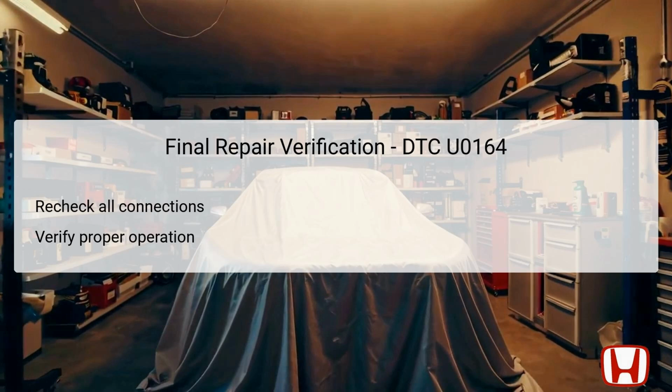It is also advisable to test the climate control unit's functionality thoroughly after repairs have been executed. This includes checking all features of the HVAC system, such as heating and cooling outputs, fan speeds, and any other relevant manual controls to confirm they are functioning properly. If all features operate correctly without generating the DTC again, the repair can be considered successful. This step ensures that any intermittent issues are caught before concluding the diagnosis.